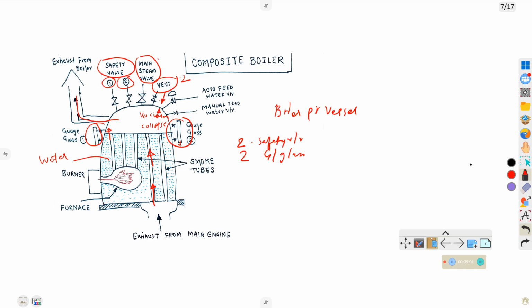If in your exit exam there is a question like that, what is the most important part? That is the gauge glass. If it is choked, it will give wrong readings, which can lead to overheating and failure of the boiler.